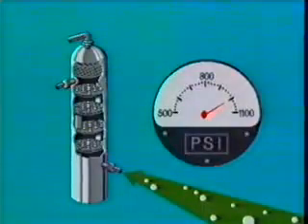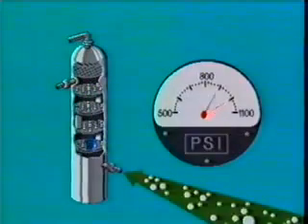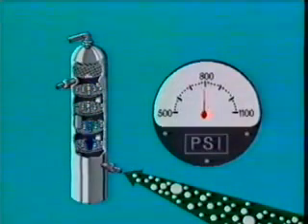First, at constant temperature, water content of inlet gas increases as pressure decreases, causing the unit to work harder to dry the gas. Secondly, at constant gas rates, the gas velocity through the contactor increases as the pressure is decreased, causing carryover problems.